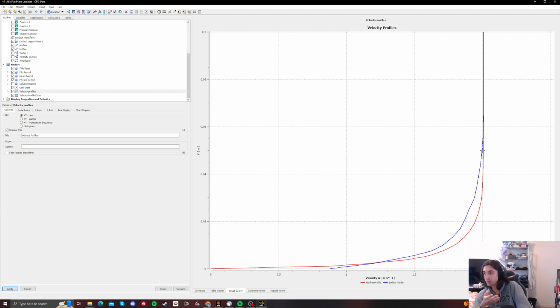They both look laminar because we are totally laminar throughout here, and the boundary layer is taller at the end than it is at the half line, but it is not linear because the half line is not exactly half of the height. It's a square root graph.